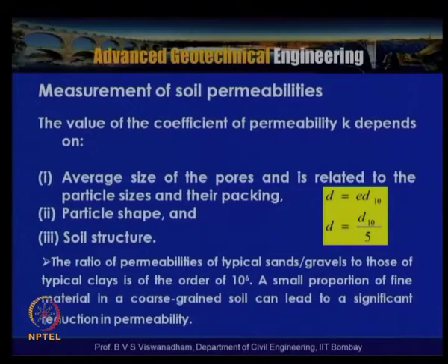As mentioned in the previous discussion, the value of the coefficient of permeability k depends upon the average size of the pores and is related to the particle sizes and their packing. We have said that the pore diameter can be approximated as void ratio times the effective particle size.